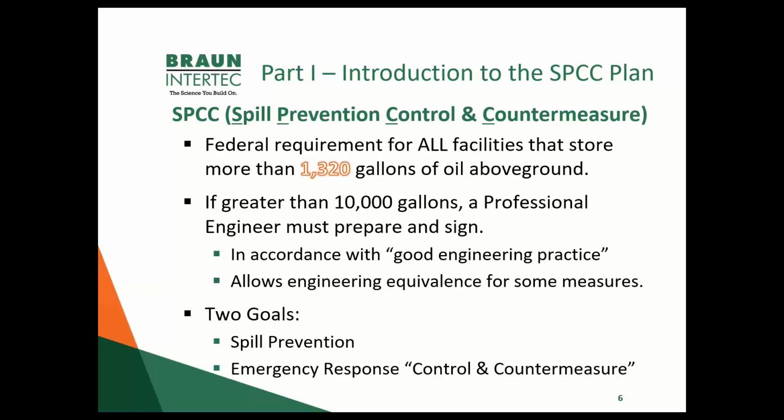The benefit of a professional engineer in helping you evaluate your facility and prepare the plan is that we have a very good understanding of what they mean by good engineering practice, which basically allows us to use our professional judgment and use engineering equivalents for some of these fairly strict oil protection, storage, and containment and spill response measures. So really the SPCC plan itself has two goals: spill prevention of oil containing materials, and then emergency response, which is really where the control and countermeasure parts of the plan come in.